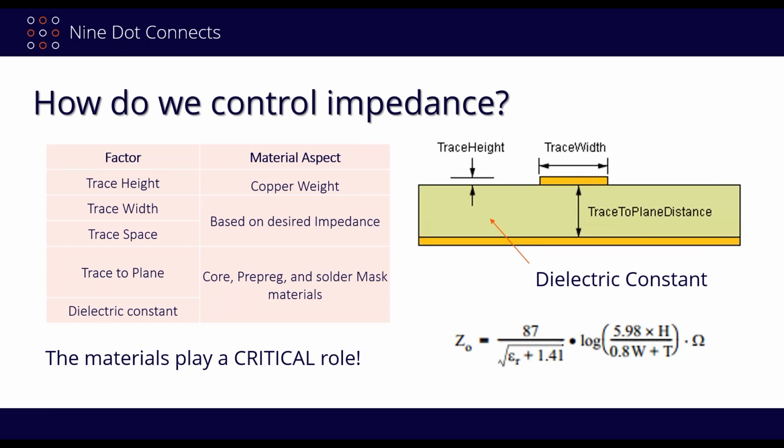You do everything in symmetry. So we'll go to a 4-layer board. For a 4-layer board, let's go to a 6-layer board. We just kind of shrugged our shoulders, and everything was fine. But unfortunately, we can't do that when we're trying to deal with impedance and high-speed design over here. The trace width and the trace height, which ultimately becomes a part of our rule set, is very heavily influenced, if not completely influenced, by not only the impedance that we need, but the stack-up that we are using. Okay? And that's what I want to give you an example of here right now.